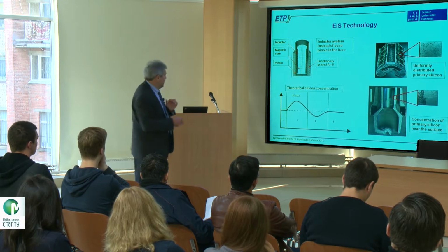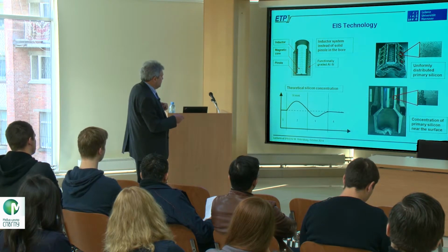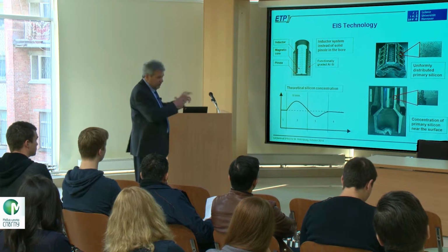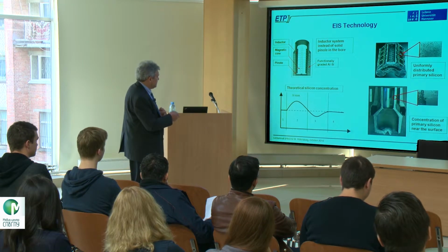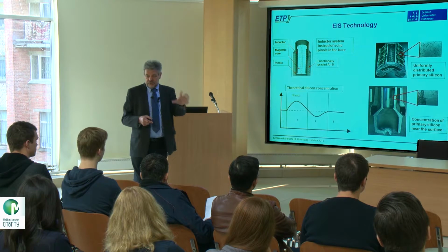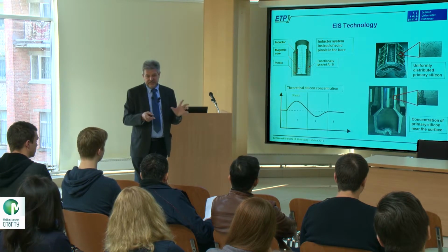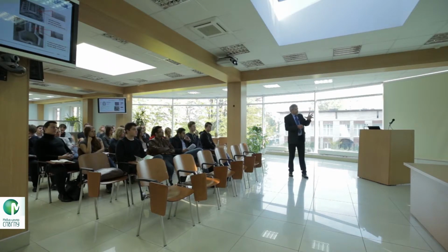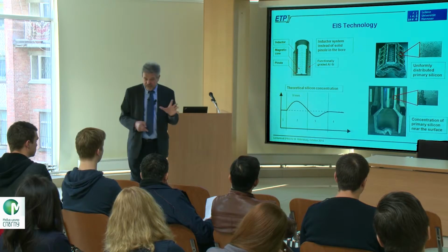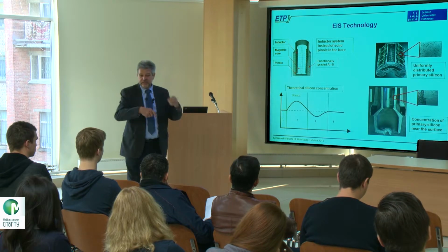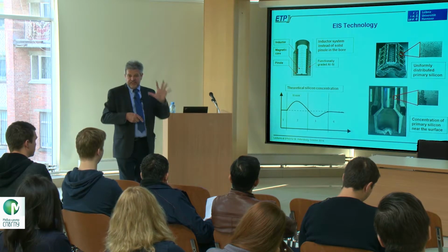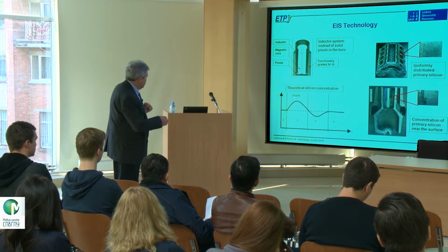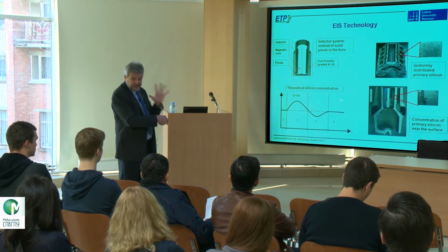Of course, normally to solidify you need some cooling. So classically, you have a mold made of sand, pressed together, but inside these cylinders you have water-cooled cylinders, normal stainless steel cylinders. If the melt comes to the water-cooled cylinders during solidification, it immediately solidifies, so you cannot realize any movement of the silicon particles. But in the zone behind, which is not immediately solidified, this movement can start, due to the Lorentz forces.